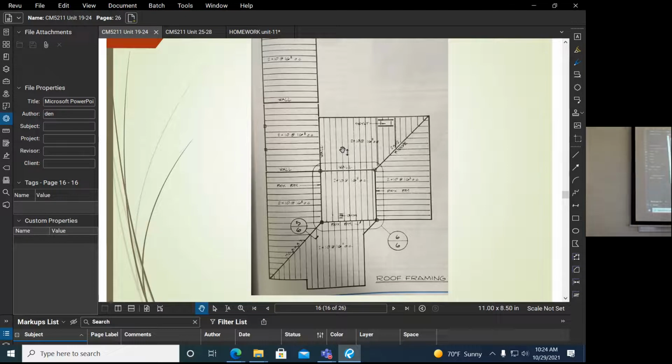Now this ridge is a 2x12 ridge, a piece of wood, whereas this ridge here is a piece of metal. And then the rest of this is 2x10, 16 inches on center. Yep, that's our roof. Why not make it uniform? I think they're trying to demonstrate metal channels. That's the way they did this design for this lake house. The lake house has these steel columns in framing below, and then goes up to the roof. It's kind of a funky framing system.